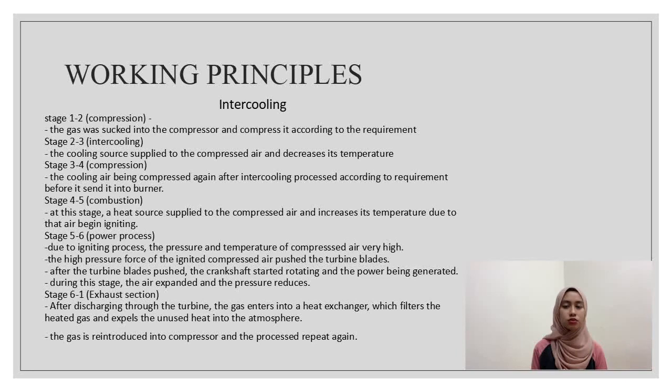Lastly, stage 6 to 1 is the exhaust section. After discharging through the turbine, the gas enters into a heat exchanger, which filters the heated gas and expels the unused heat into the atmosphere. The gas is reintroduced into the compressor and the process repeats again.